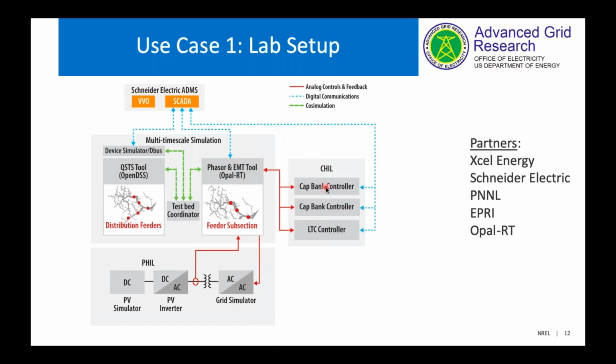In this case, the ADMS has control over an LTC, load tap changer, at the feeder head, and it also has control over capacitor banks on the system to regulate voltage. So we implemented those controllers in hardware, and then we included a PV inverter as power hardware in the loop.